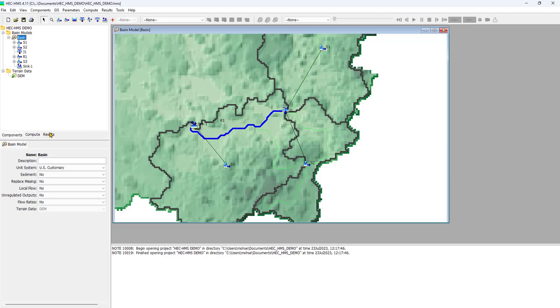In this simple example, I'm going to define a hypothetical design rainfall of 50 year. So I have gone to NOAA Atlas 14 and I have noted down the amount of 50-year rainfall in my study area, and that's one number in inches. I'm going to use that one number in inches and create a rainfall distribution over time and input that into the model. How do I do that?